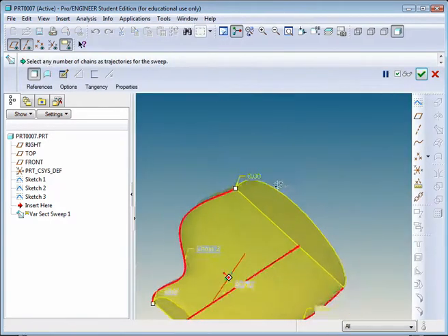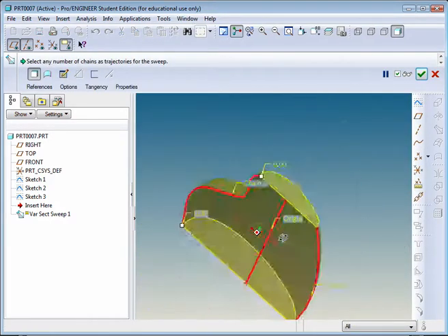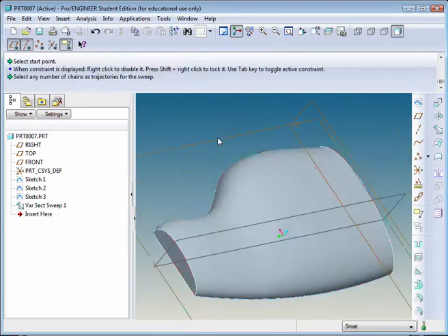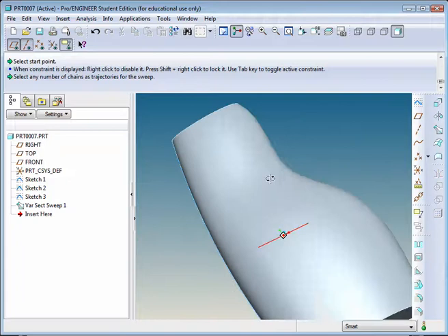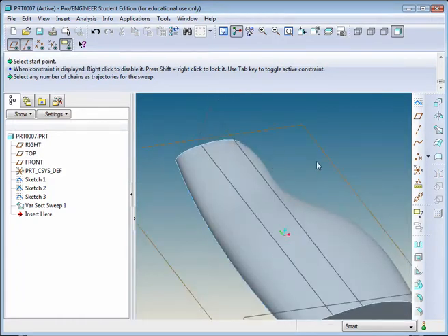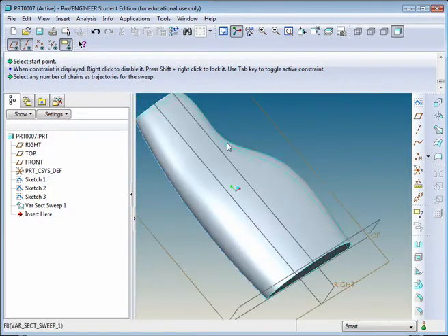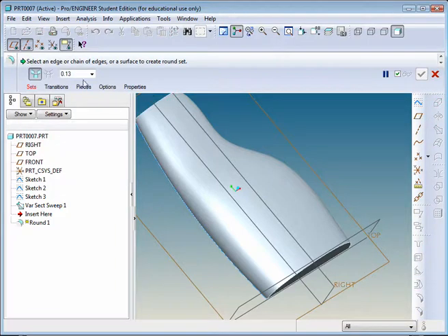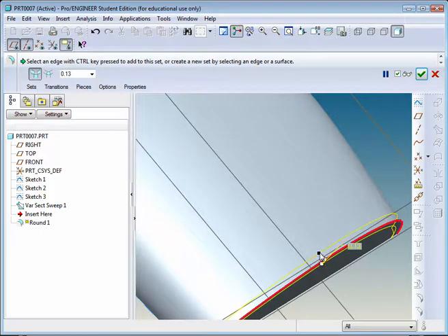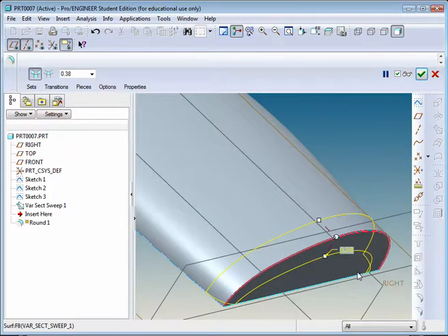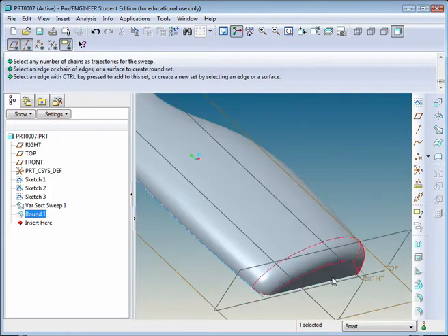And we can see a preview of our bottle. Let's make it exactly 1/2 of it. Hit the done tool. And there we go. Now, before we mirror it, you could start putting the additional features on, like the fillets and things like that. And then also there's a little detail in here. So for that, let's go to the fillet tool right here, or the round. And 0.13 is fine for this, although we could go ahead and click on the edge and drag this out a little bit further just by grabbing the points, manipulate it till we like what we see. In the middle, click to apply it.